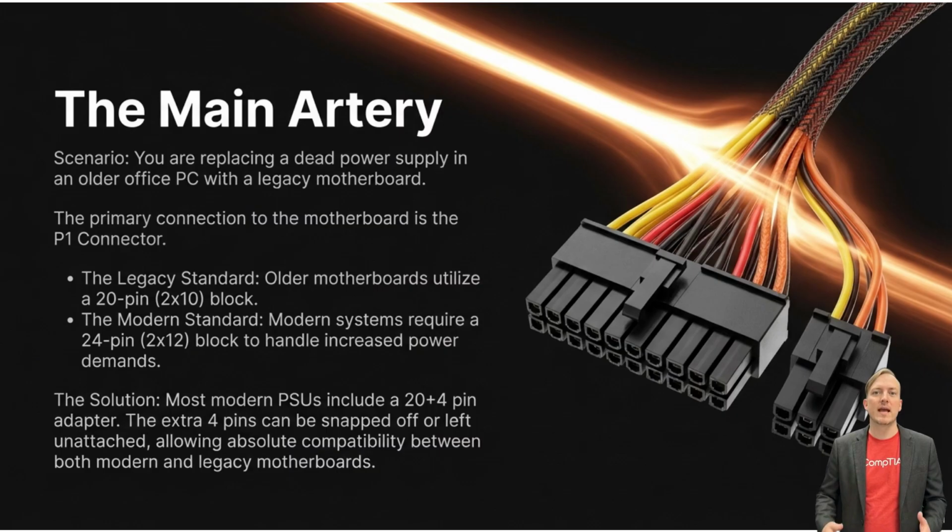Scenario: you are replacing a dead power supply in an older office PC with a legacy motherboard. The primary connection to the motherboard is the P1 connector. The legacy standard utilized a 20-pin block. The modern standard requires a 24-pin block to handle increased power demands. The solution? Most modern PSUs include a 20 plus 4 pin adapter. Those extra 4 pins can be snapped off or left unattached, giving you absolute compatibility across both modern and legacy motherboards.